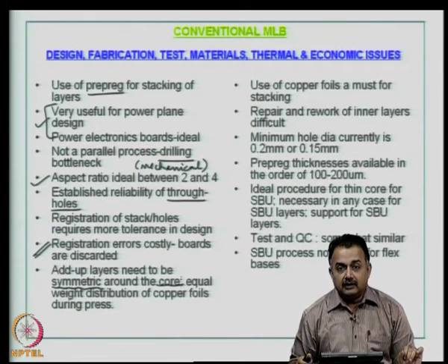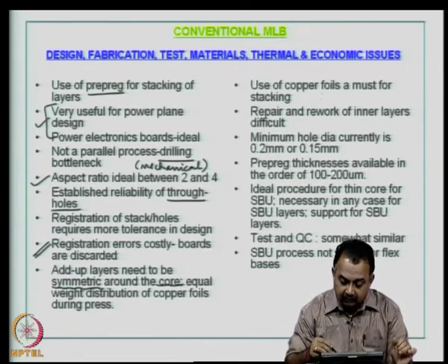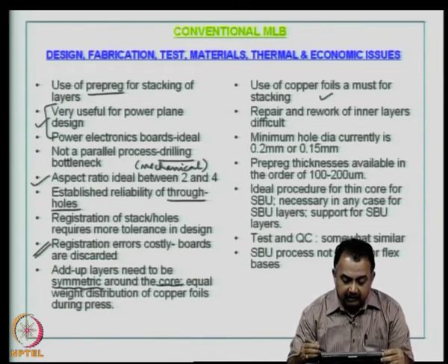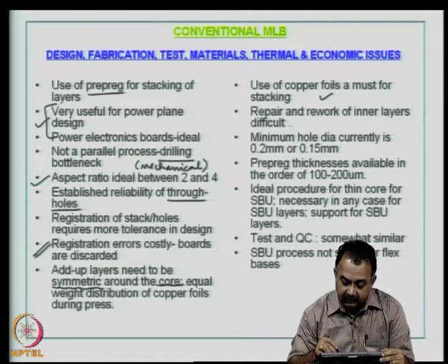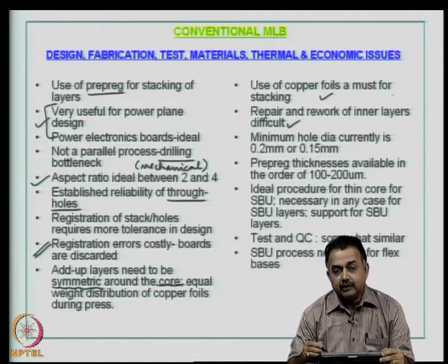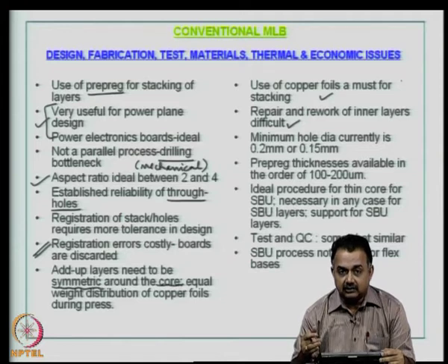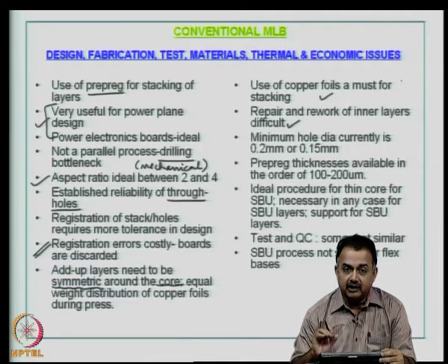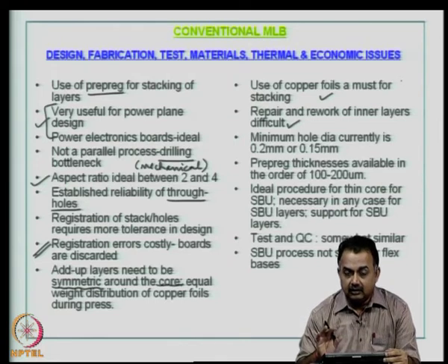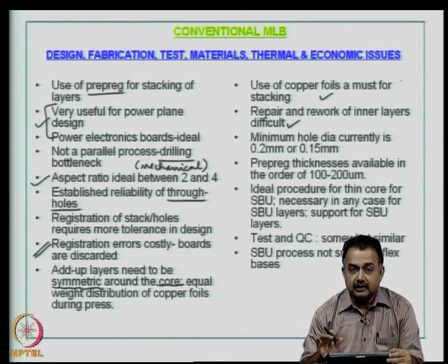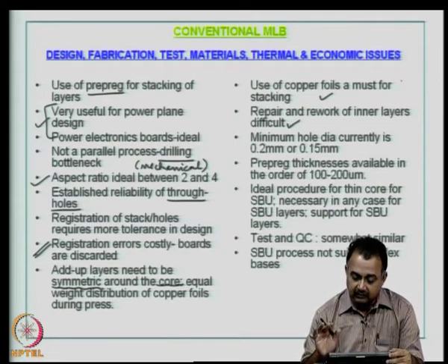Use of copper foils is a must for stacking. So, you will use a prepreg as well as copper foils. Repair and rework of inner layers is difficult. So, we have seen at least a couple of methods to fabricate conventional multilayer boards, and the inner layers have to be immediately quality checked for electrical shorts and opens as well as any process defects on the surface.